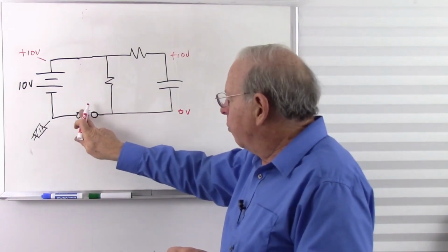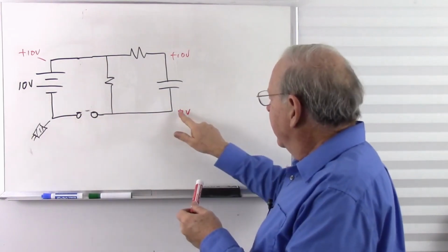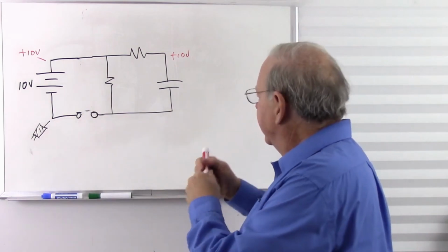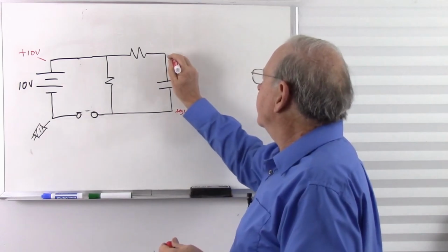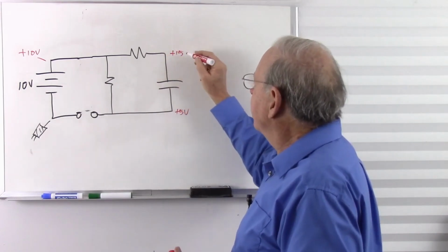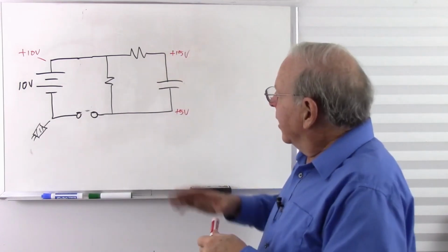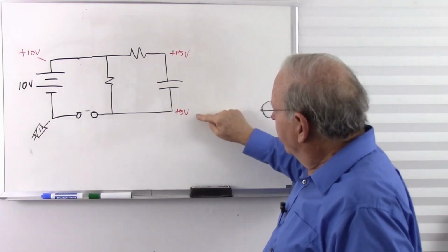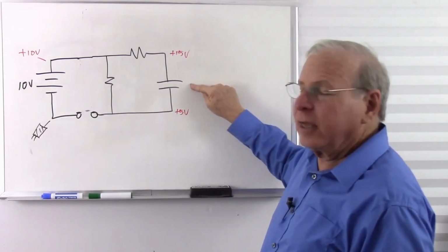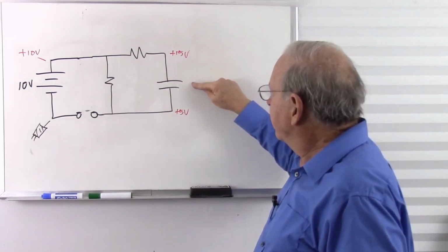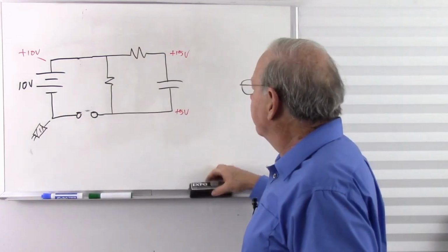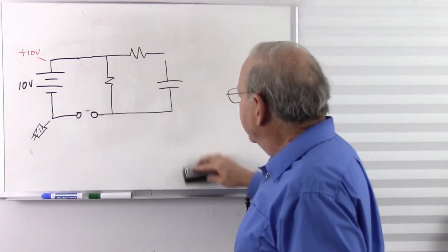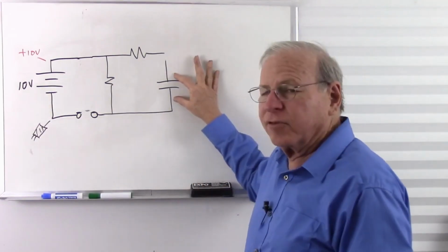When we open that up, what happens? This voltage jumps up to 5 volts. That jumps up to 15 volts. And then as that capacitor discharges, this voltage goes up towards 10. This voltage drops down towards 10. And after 10 seconds, because it's got 2 resistors to go through, the voltage difference across this capacitor becomes 0.